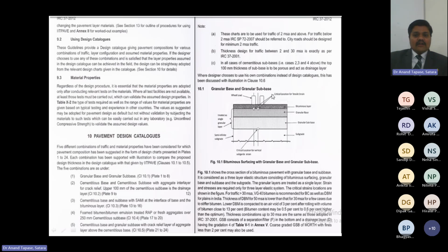Well, pavement design catalog. I'm pointing out the first figure, what layers they have taken, that can be seen. There are altogether 1, 2, 3, 4 layers they have considered. Here you can recognize what I was talking about, that the bituminous layer is considered as a single, one layer. The two wheels are considered. Researchers can consider a single wheel or a combination of two. We can consider two wheels as far as the IIT PO is concerned.